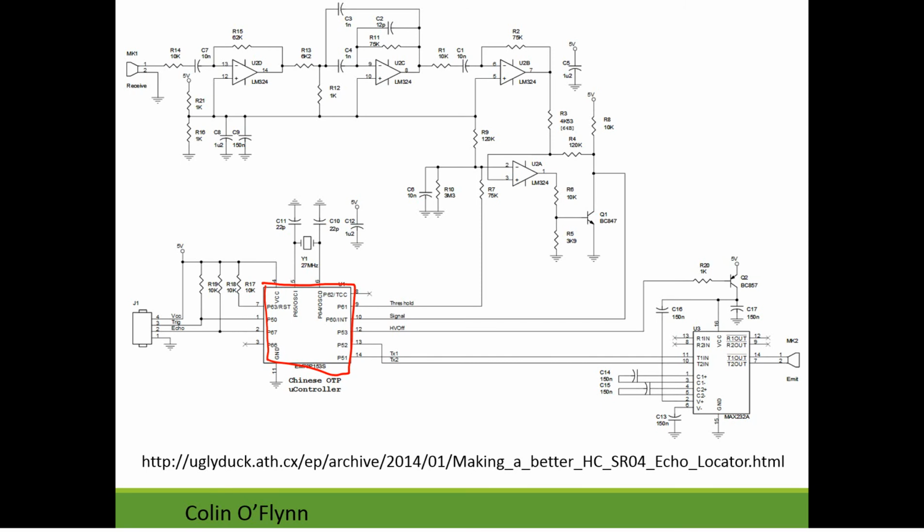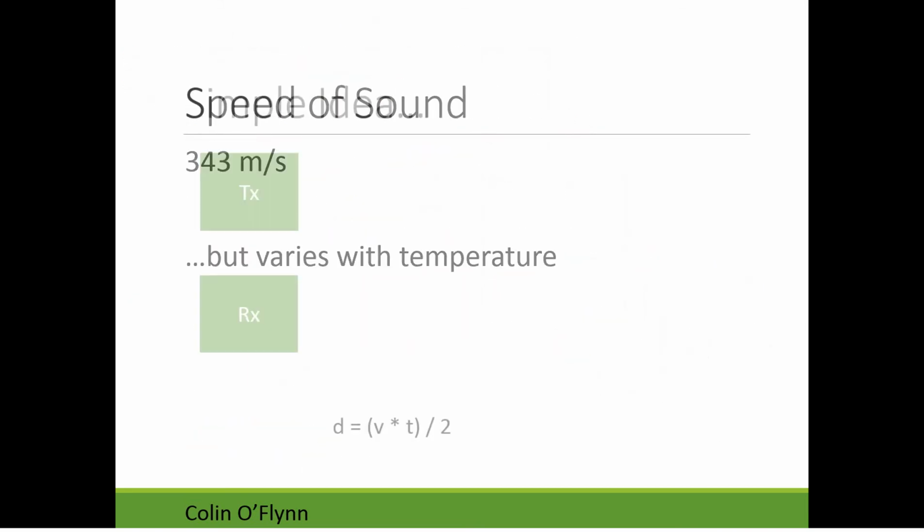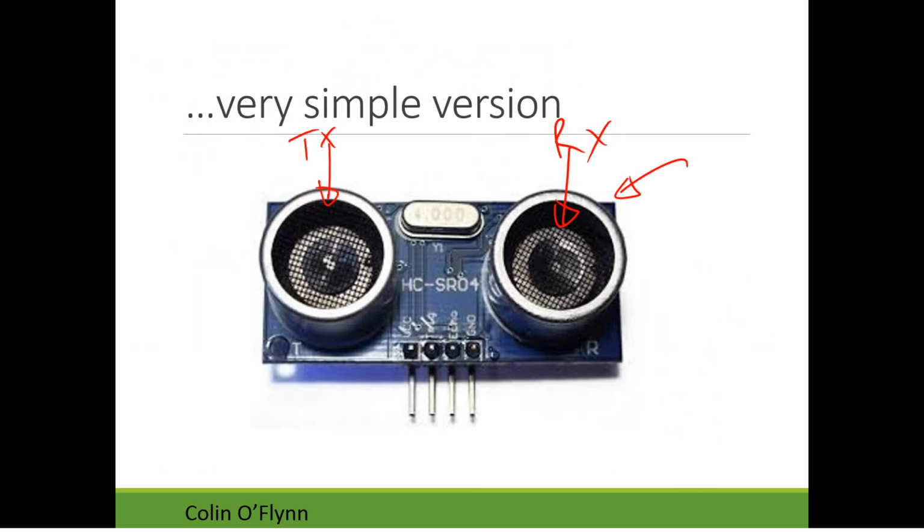This is what's known as a one-time programmable, or OTP, microcontroller. It means you can program it only once, and then you have to throw it away if you want to change the program, so you don't get your program wrong, because it's not updatable. But the idea is that someone's made the program, debugged it, got it to work, and then loaded it onto the chips in the thousands or hundreds of thousands, to populate these boards and sell them to you as cheaply as possible, because the microcontroller is so low cost.